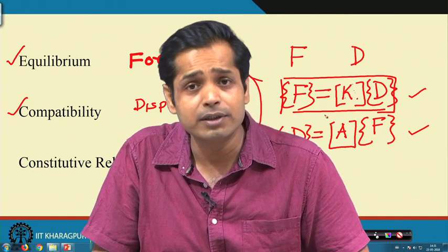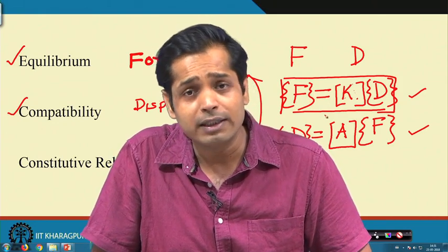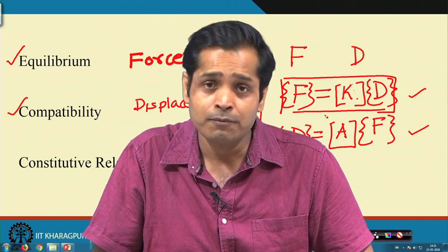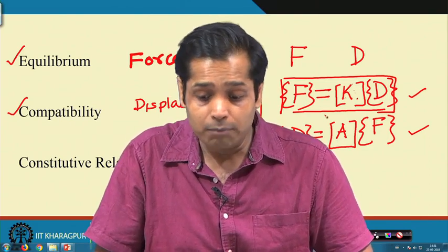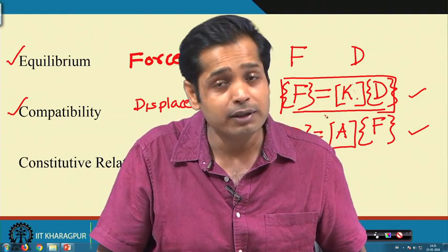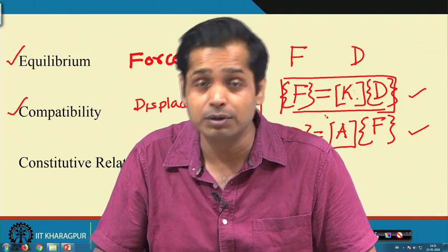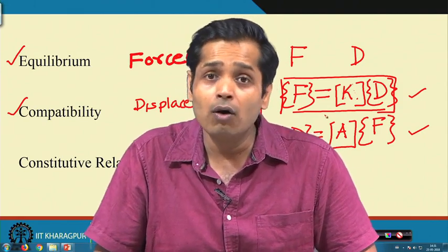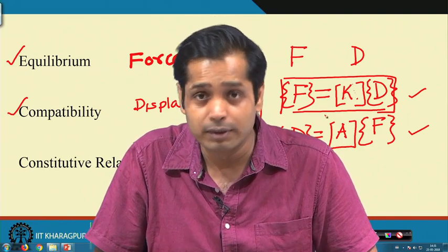The concept is important, but how the concept is translated into a method is also important, because the force method, method of consistent deformation, slope deflection method, and moment distribution method are all based on the flexibility or stiffness definition of the force and displacement relation.